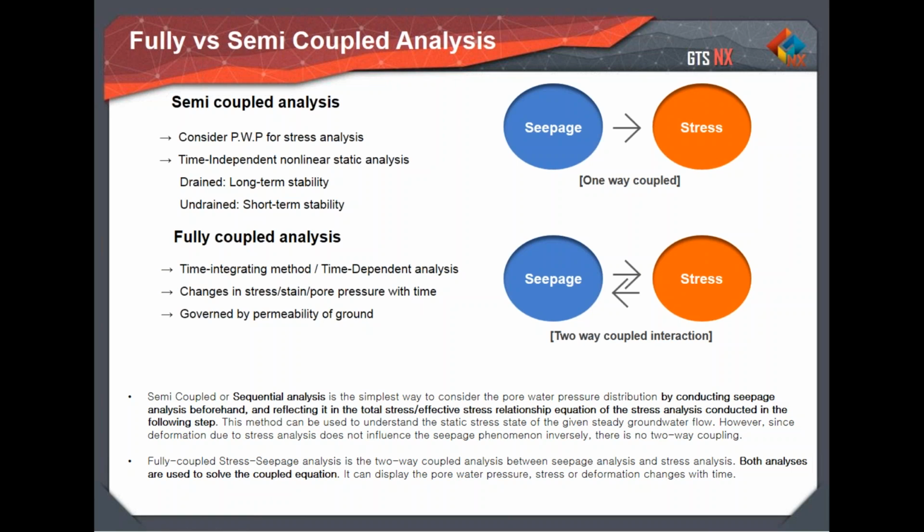So just a quick recap. Recently, maybe last month, if you attended one of our trainings, we did analysis for what would be semi-coupled, which is the seepage-stress sequential change. So you can think of the semi-coupled analysis as a sequential analysis. So basically, you have one stage where you consider the seepage analysis, you create results for pore pressure, and then those results of pore pressure are passed on to the next stage, which is a stress analysis, so that they can consider the pore water pressure in those cases.